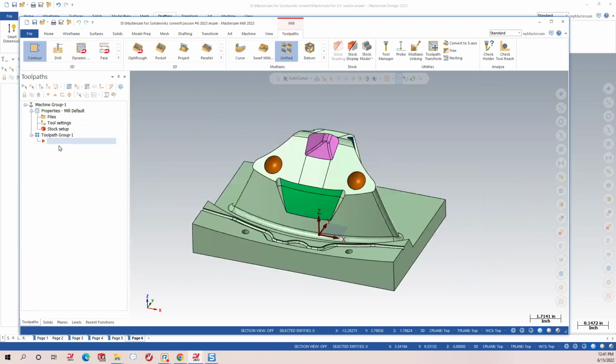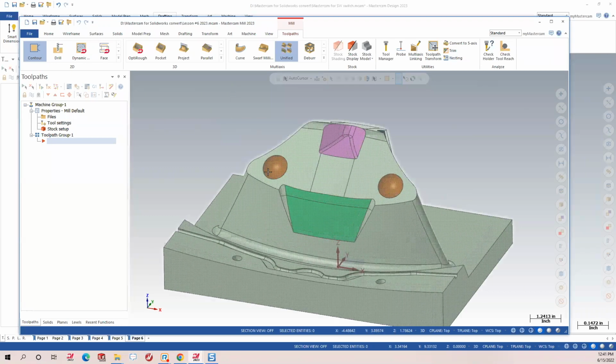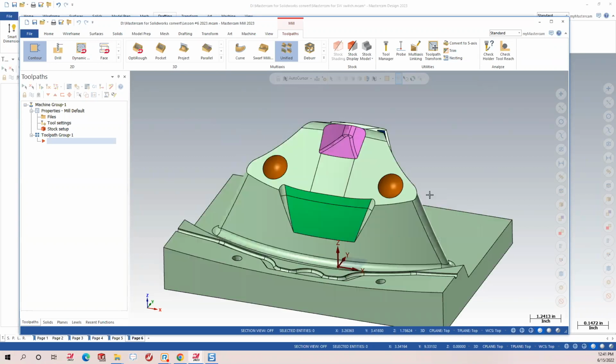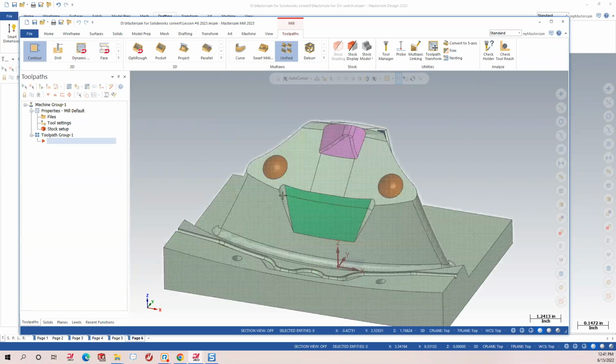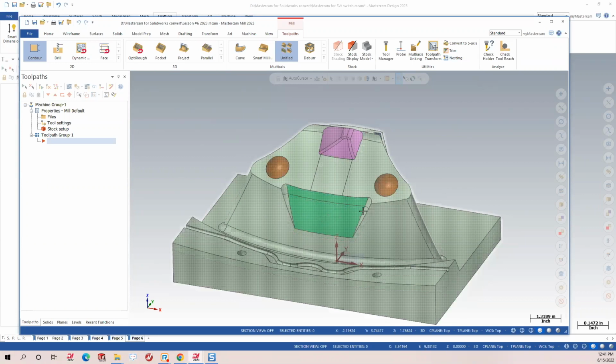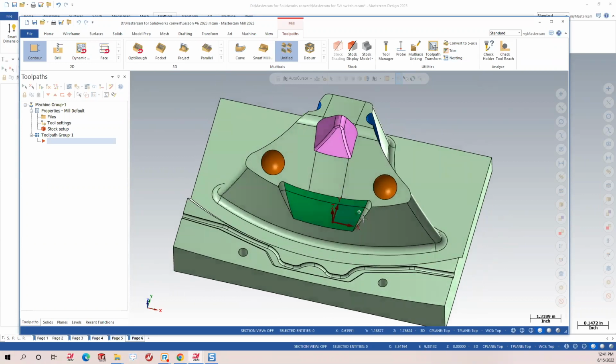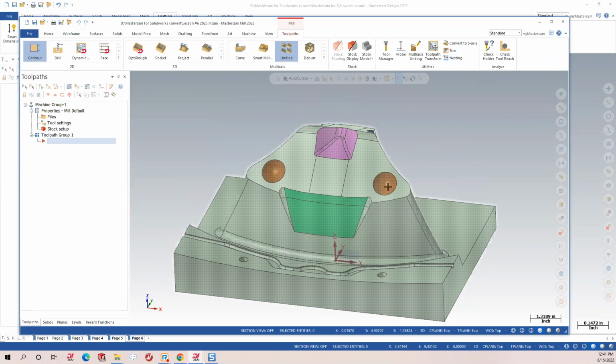As I want to machine it, you go through your stock setup. It is quite a bit different in 2023, and it's a whole other subject. I wanted to get through the whole topic before we venture down that, if I do get that far, but I want to make sure that these edges are sharp. So I really can't maybe waterline the whole thing, or I want to put some plugs inside this geometry to fill it in so I can machine it the way I would want to, and then come back and machine these individually to make sure these edges stay sharp, the way they make sure the geometry, or optimize motion of my toolpath to get really what I want inside the geometry.